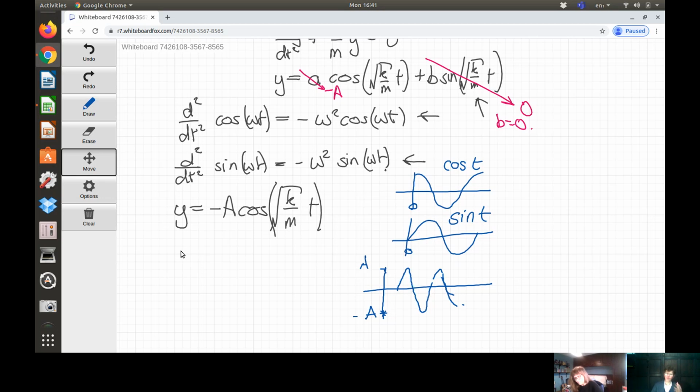Yeah, I guess we could also talk about why we wouldn't bother with the decay unless it was very large. Because the reason we've been making a model like this is to work out, are the two wires likely to bash into each other? And that's probably going to happen in the first oscillation or not at all. So unless the decay is so large that it significantly affects the amplitude in a single oscillation, we probably don't care too much about it. Because our model will only be valid until one wire bashes into another, after which very different physics will take over.